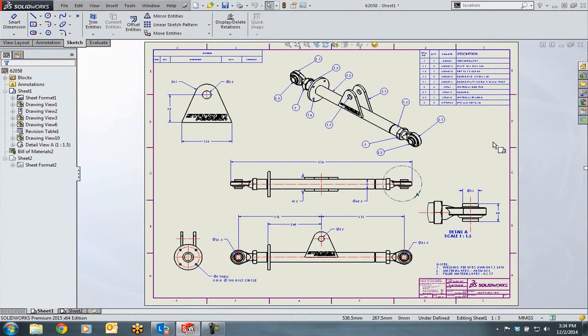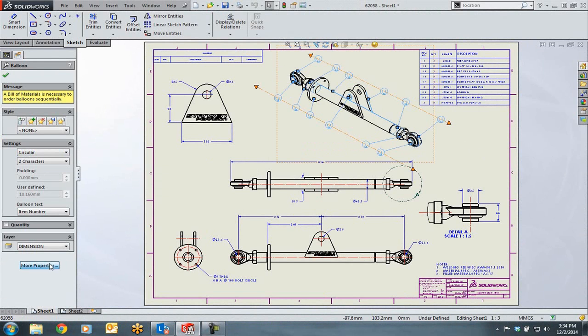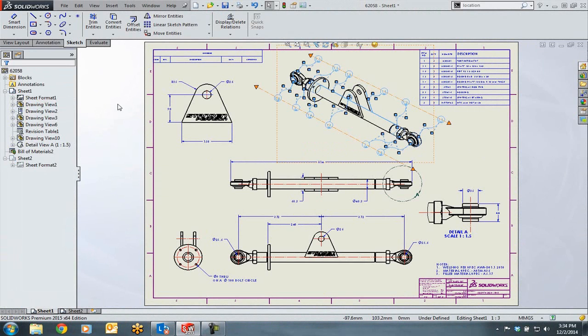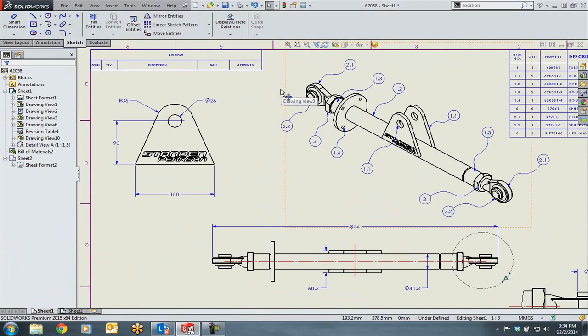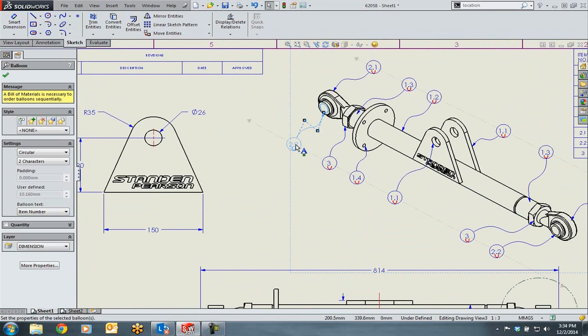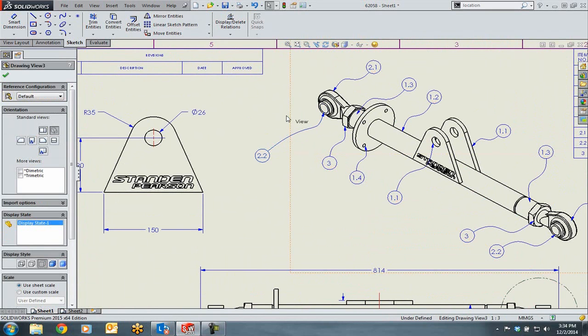Drawings are important to many of our customers, and with this release of the software, SolidWorks continues to add functionality. The first thing I'd like to show is how we can move from the standard straight leader to the new leader style, the spline leader. This leader is especially beneficial when working on pattern drawings, or when you're just trying to place an annotation in that hard-to-reach part of a drawing view. These splines are, of course, fully editable.